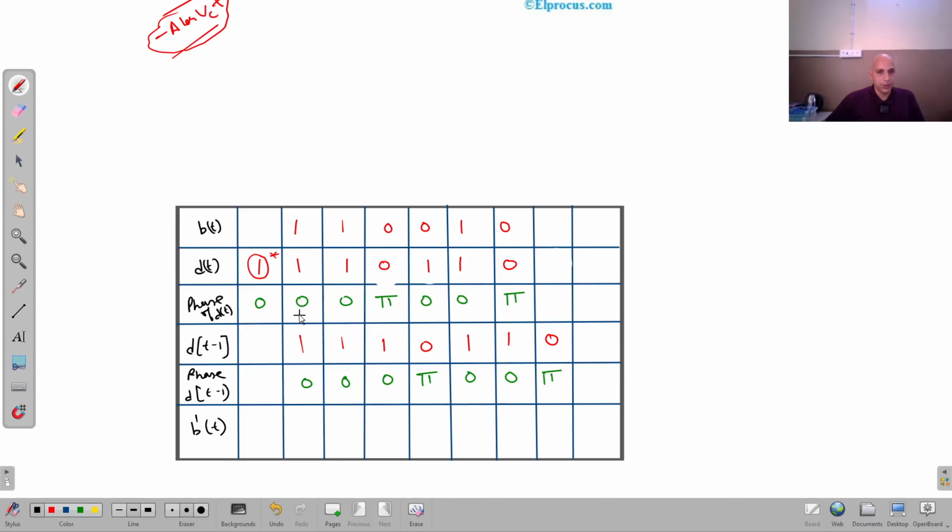Here it is the phase of the original bit and the phase of this same phase, right? So the bit generated is 1. So here same phase, right? This one bit generated is 1. Now here it is the phase difference, 180 degree out of phase, bit generated is 0. Here again there is a phase difference, so bit generated is 0. It is same phase, bit generated is 1. It is phase difference of 180 degree, so bit generated is 0, right?